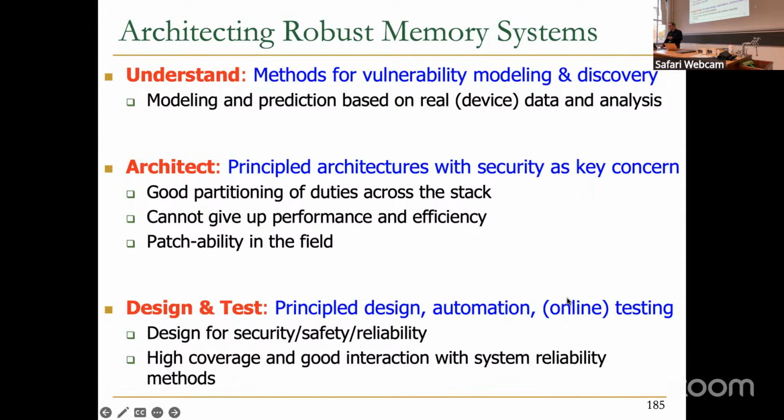How do we actually do testing, for example? This is actually a very difficult problem. We have multiple papers on profiling, testing DRAM chips, different types of errors, retention, RowHammer, RowPress, RowHammer plus RowPress. So testing becomes very difficult. And testing is actually the biggest cost of manufacturing a chip today, whether it's a processor chip or a DRAM chip. The biggest cost is really testing and verification.